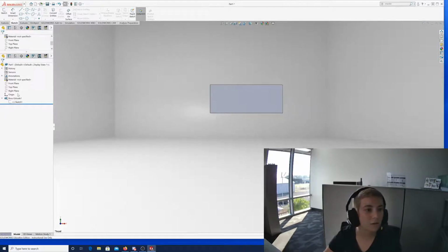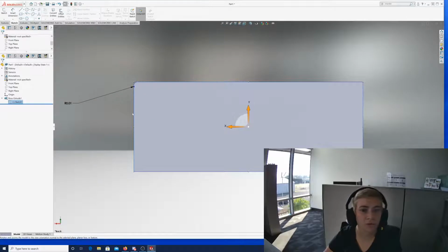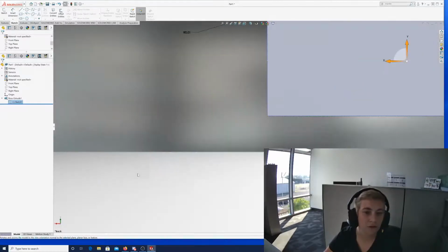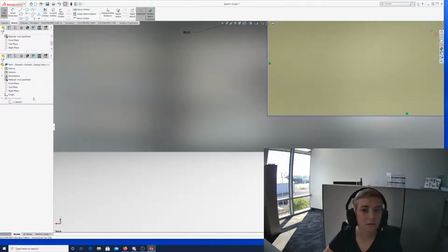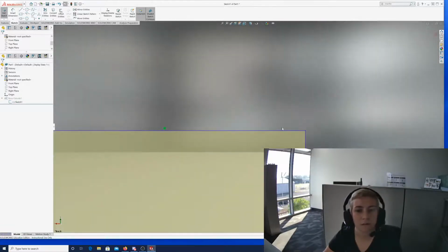One second. So if you go back to your sketch and you do the normal to thing, if you started your sketch on an origin, it'll show up as soon as you go normal to the sketch. Let me get back in here again. You know what?